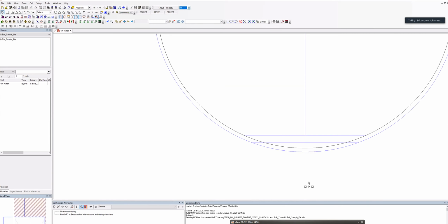As we move down here, there are some horizontal lines, and these are normally marking the flat edge of a wafer. A silicon wafer will have a flat edge. Normally, the 100 wafers that are most commonly used will have a flat edge, or the major flat edge, pointing downwards. And these are normally assigned the reference of one of the crystal planes. So when you do a design, and the design is dependent on the orientation of crystal planes, you always need to align your design with the flat edge. And therefore, in your mask, it depends sometimes on how far up the flat edge is going, so there are 2 different reference points here for you to use.